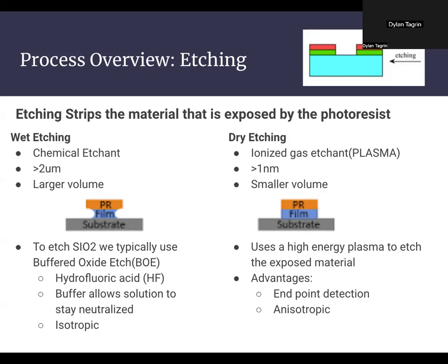What are the downsides of dry etching? Is it just slower? I think it's less selective. With etching you can do a lot more with selectivity in terms of material selectivity. Oh, I get it. So if you're doing multiple film layers, you'd basically have to use wet etching, because dry etching would cut through multiple layers at once, so to speak. Reactive ion etching or something.